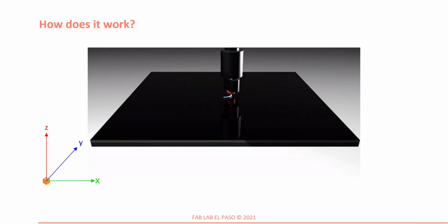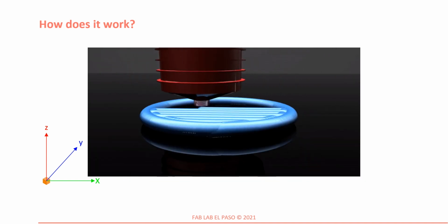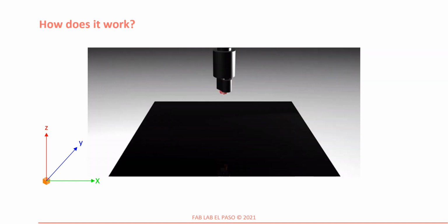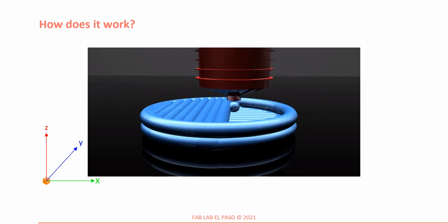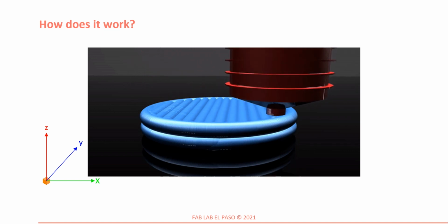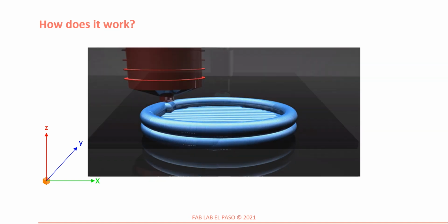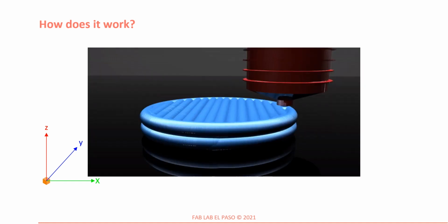Now let's take a closer look at this process. First, the heated material is dispensed through a nozzle along a platform in the X and Y directions. The shape is filled in, then either the platform drops down or the nozzle is raised up a bit along the Z-axis. The nozzle will dispense a second layer of material on top of the first layer. This process is repeated over and over until the final three-dimensional shape has formed.